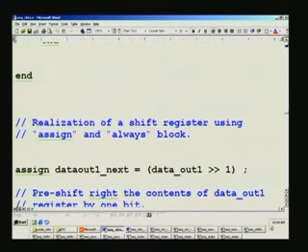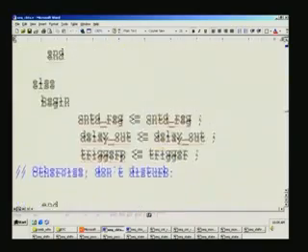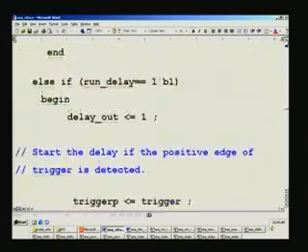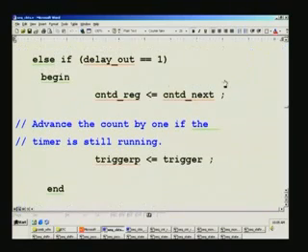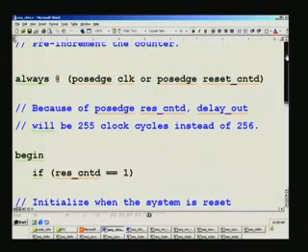So why 4 is here, that if reset will be negative edge reset. First if we had put it as here instead of this, we had used a negative edge reset_n, and because we have combined that, here it happens to be the same condition, whether this condition takes place or this.